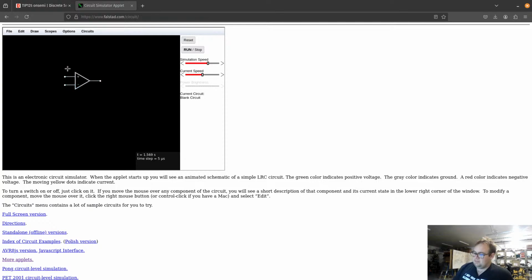I think that it will be just easier. Then we won't worry necessarily about the inconsistencies, like that there would be an I bias and such through here. We'll just assume that they are perfect. There's no current that goes into the input. The two inputs have the same voltage or want to be at the same voltage. All of that jazz.